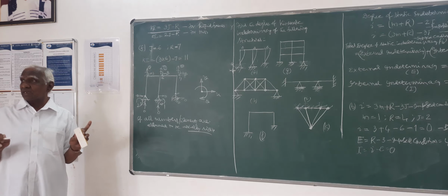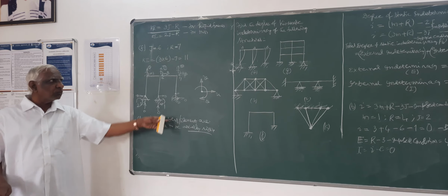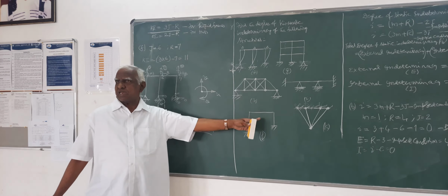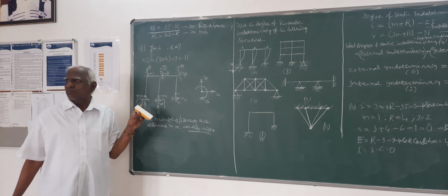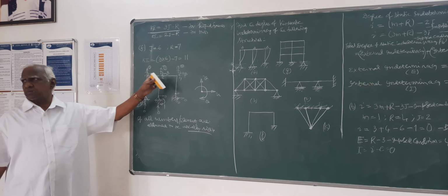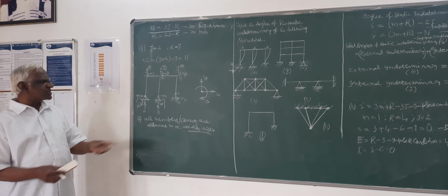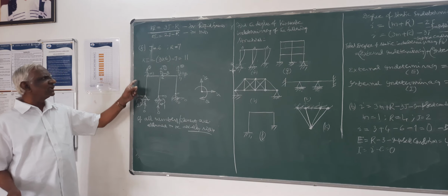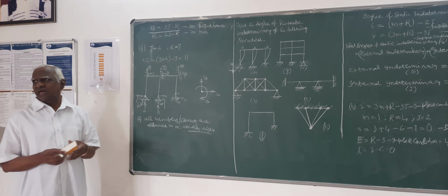This is a very basic, important thing because in the stiffness method, we talk only about kinematic indeterminacy, the unknown displacements at all the joints. So you have to correctly identify which unknown displacements are possible at each joint. Now you see, the moment you assume all members to be axially rigid, the rotation of course will be there.